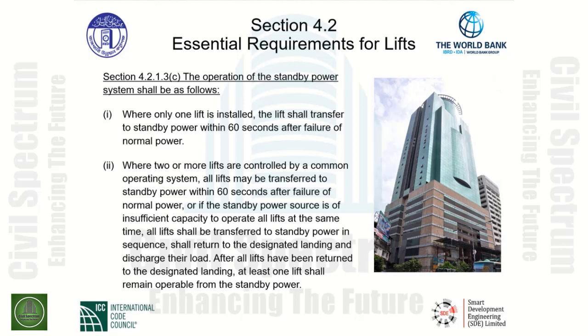Item 2 is where we have 2 or more lifts that are controlled by a common operating system. All lifts in this case may be transferred to standby power within 60 seconds after failure of normal power.